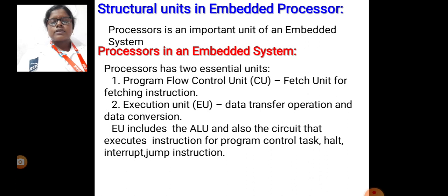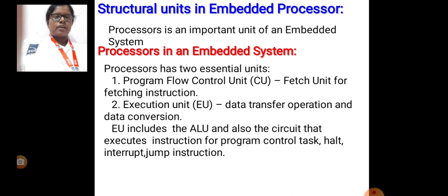Okay, now if we need to design the system, the system designer must know the following things. First one is the instruction set and maximum bits operated in a single arithmetic logic operation, clock frequency in megahertz, and processing speed in million instructions per second. Also the processor's ability to solve complex algorithms in meeting deadlines for their processing. Okay. Embedded processors are classified into three types.